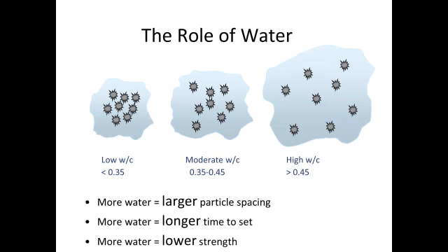And another element that I wanted to reinforce is, when you make concrete, you have all the ingredients we're putting in, the sand, the rocks, and what's important is the cement particles and our pozzolans are finite particles. It's not a mushy sauce. They're finite particles. And the less water you have, the closer those particles are together. And that means that they can start reacting faster, they can start connecting up faster, there's less space, so there's less excess water, there's less porosity.